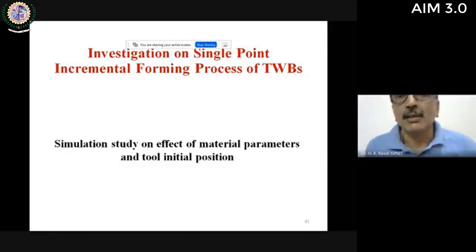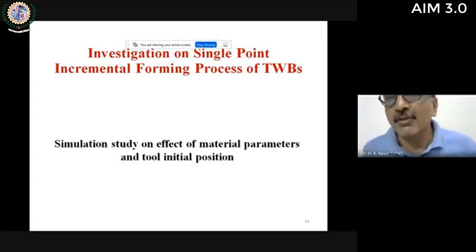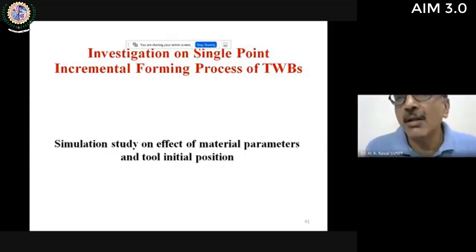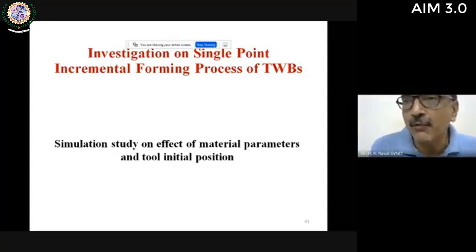just to have economy in manufacturing, in terms of cost saving of material without much compromising the strength. Usually it has found applications in the automobile industry, where some portions require high strength material and some portions are only required to support things. You can compromise with the material strength, the material types, or the material thickness, and thereby use material combinations or thickness combinations, which can be called a TWB, tailor welded blank. These blanks are welded prior to forming.